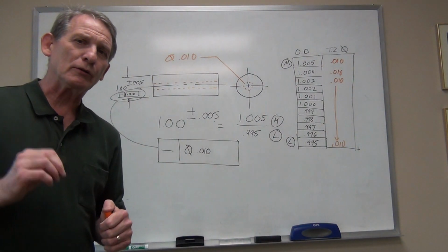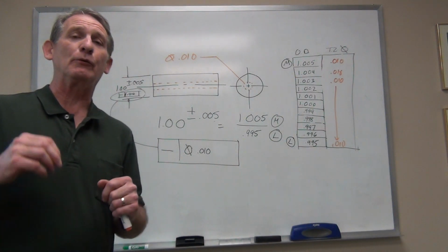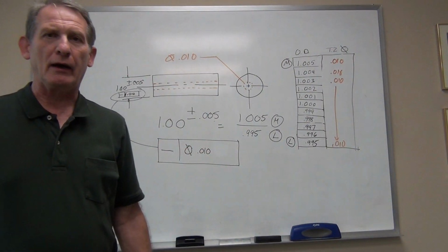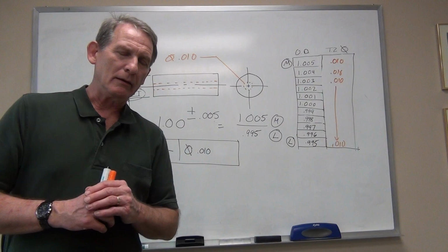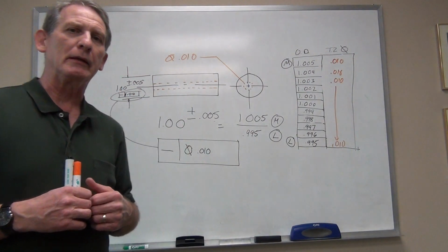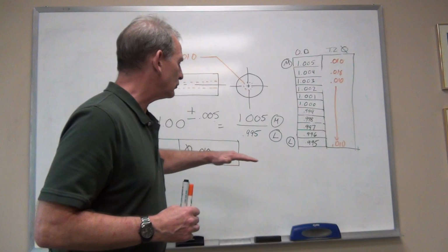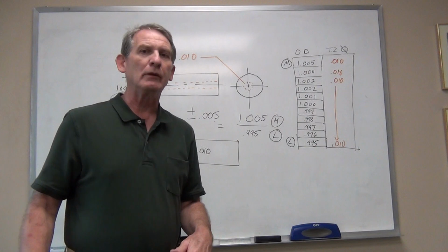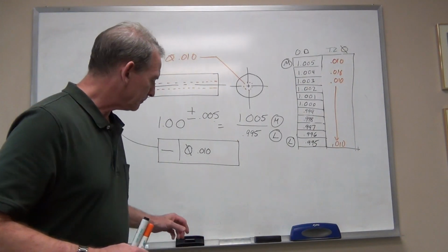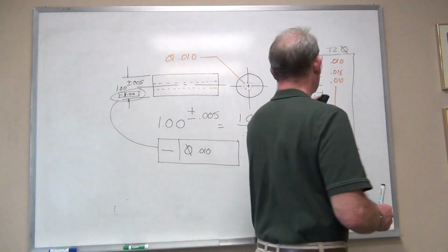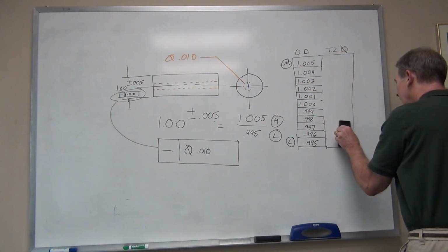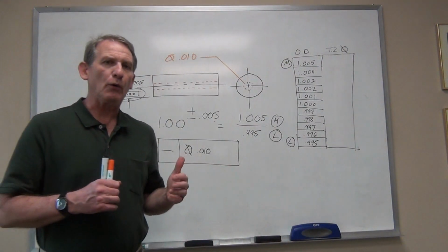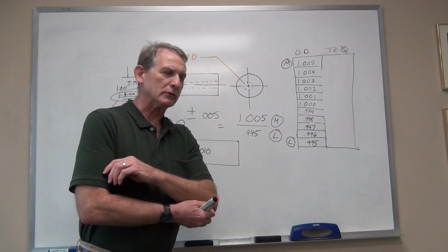That tolerance zone starts at 10 thousandths, it ends at 10 thousandths, and it will always be 10 thousandths because there is no material condition modifier there. You have to sort of imagine that there's an S there, but if there's nothing there, the tolerance zone does not change. Whatever is stated in the feature control frame, that's the size of the tolerance zone, and that's what it will always be. Those are the easy ones. But they don't take advantage of the power of GD&T to allow you to adjust the tolerance zone.